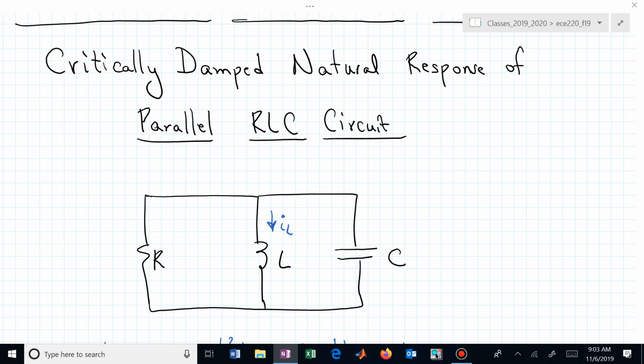And last time maybe I confused some of you by saying what makes this a tank circuit. I was just trying to get us comfortable with how we might introduce oscillatory behavior. When we have a tank circuit, that R goes away. The resistance goes to infinity. We open up that particular branch, and now we just have this oscillation of energy stored in the magnetic field of the inductor being tossed back to the energy stored in the electric field of the capacitor. And that just goes back and forth in a sinusoidal manner. The sinusoidal behavior depends on the L and C values. The natural frequency is 1 over the square root of their product, L times C.